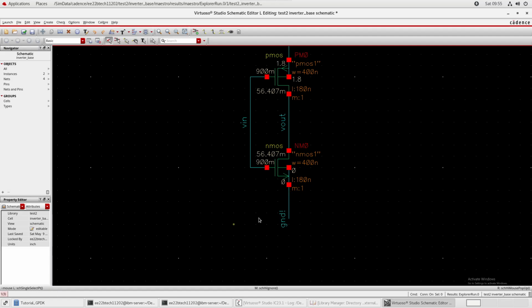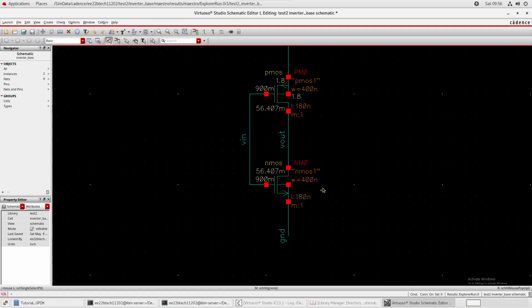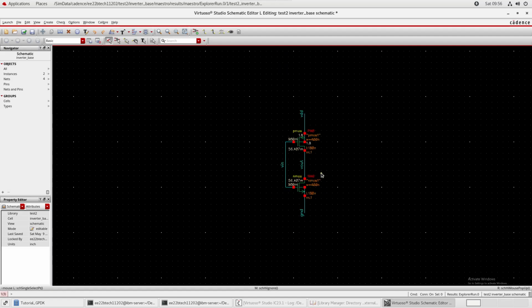So this is defined to be 0 volts. It's just a way to tell the simulator that this is absolute 0 volts, right? Because you need some reference for all of your voltages. So never ever include GND and the exclamation mark in your designs. That will also cause issues because that doesn't exist in reality. You will have some node as your ground, not some value which is some absolute 0, right?